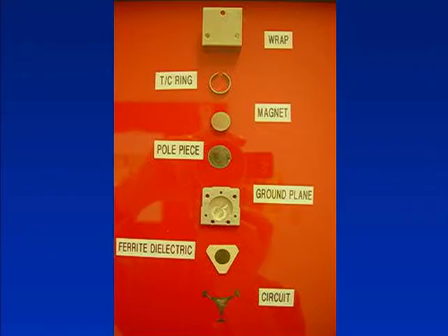This shows the components of a coaxial isolator. There is a circuit down the very bottom, and it joins the three connectors, the coax connectors, and it's surrounded both sides by the ferrite, or the black material, which is surrounded by dielectric, which just helps us match the unit and stop reflections. Then there is a ground plane. The ground plane completes the transmission line for the energy to flow around the circuit.